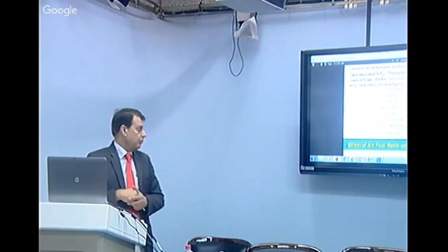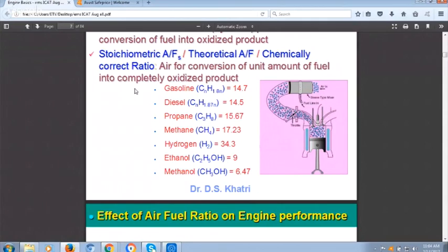Even in a very advanced car, what they do is put a pressure sensor across the air cleaner element and measure the delta P there. In a new car, suppose the pressure is 95 kilopascal, so the delta P is 5 kilopascal between the atmosphere and the engine side. When the delta P increases, I glow a light, because I have put a pressure sensor, and that will indicate now clean the air cleaner, because otherwise it is difficult to know the pressure drop across it. But that requires additional cost. You can put pressure differential sensors and a light in the vehicle, and it will glow when the pressure drop increases to the terminating pressure drop.